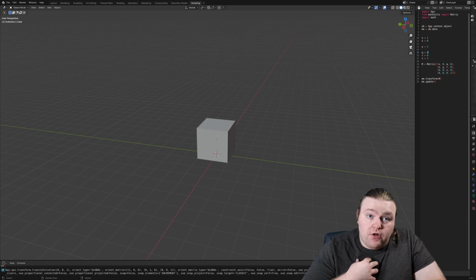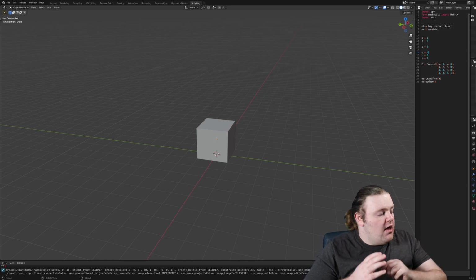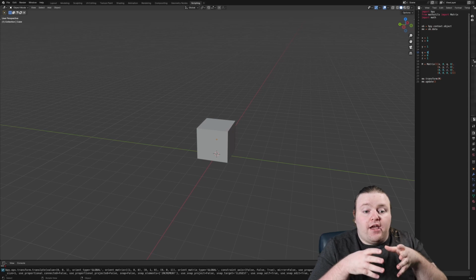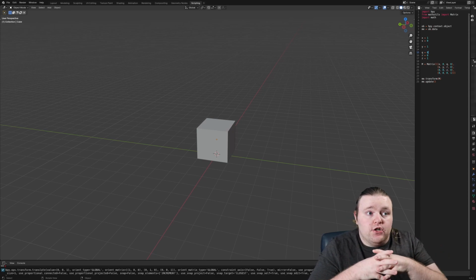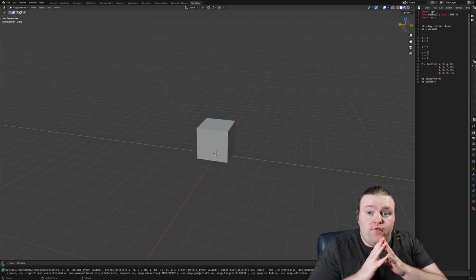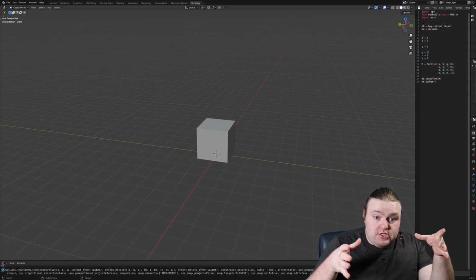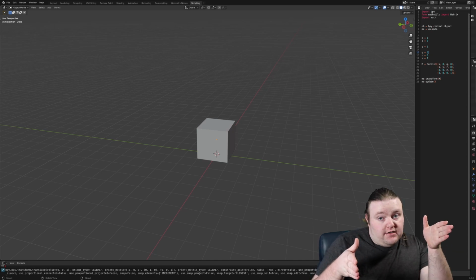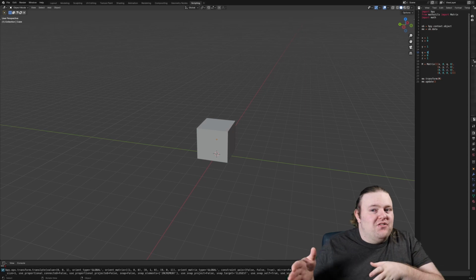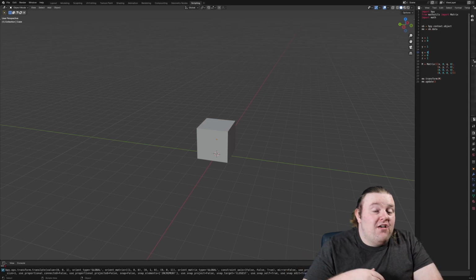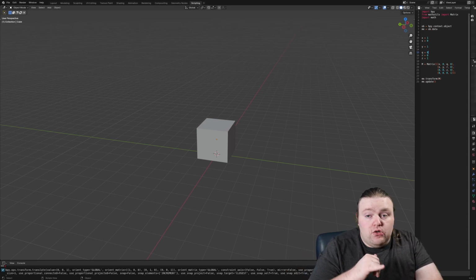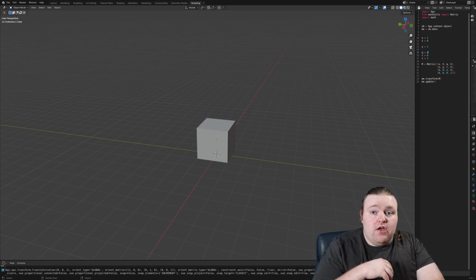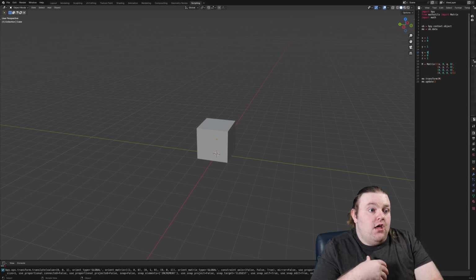Something else that I personally have already experienced is that the dimensional accuracy from the different axes of my printer is not the same. That causes a problem for technical parts where I've printed a 100 millimeter by 100 millimeter square, but one side is 99.75 and the other side is 99.2. So just a unilateral XY compensation scale that applies to both the same is insufficient.